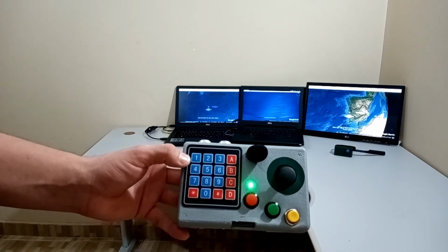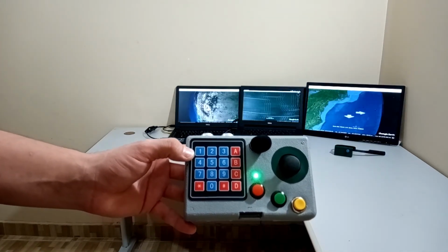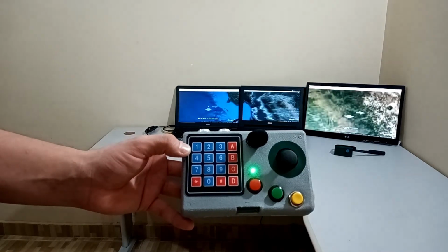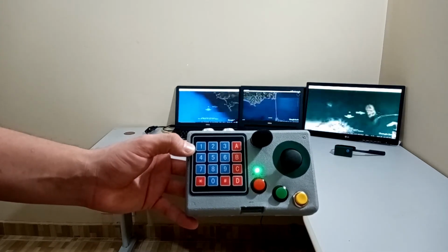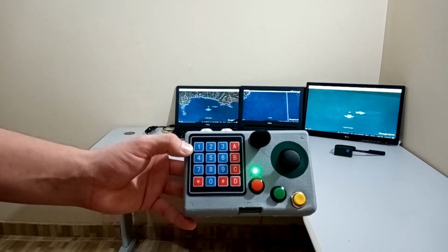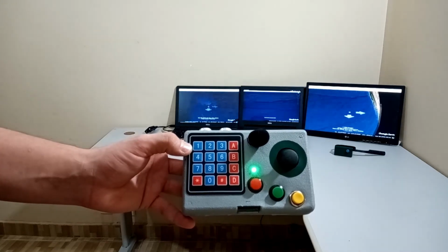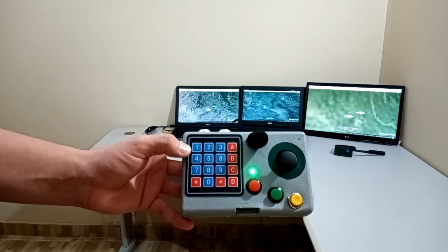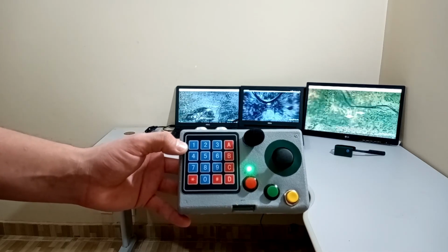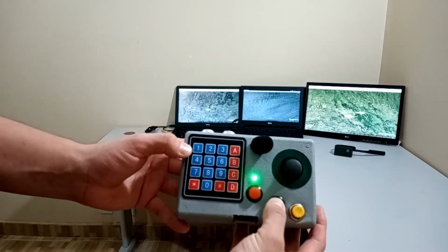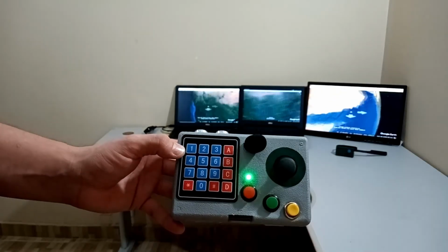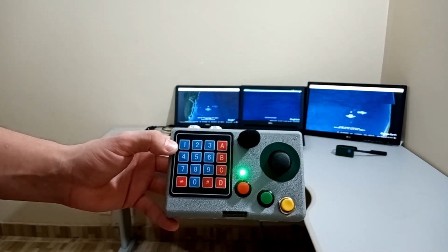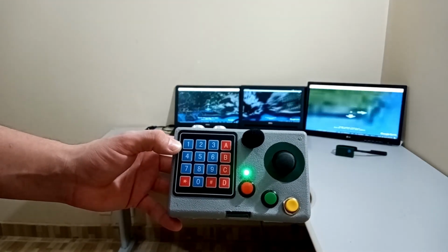The application works integrally for both controllers. Both have a Bluetooth connection to receive user updates. In order for the controls to work correctly using Wi-Fi connection, it is necessary to allow their connection on the main computer's firewall, as the device makes a connection via socket through port 8000.